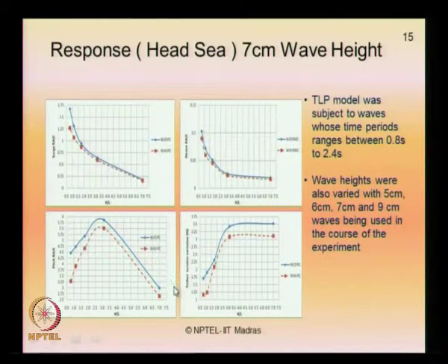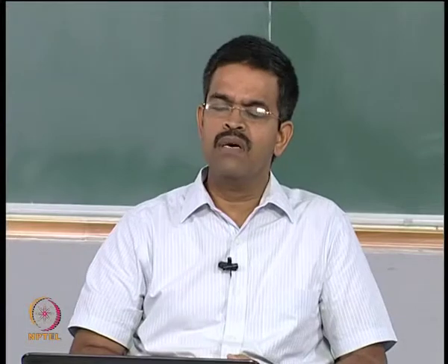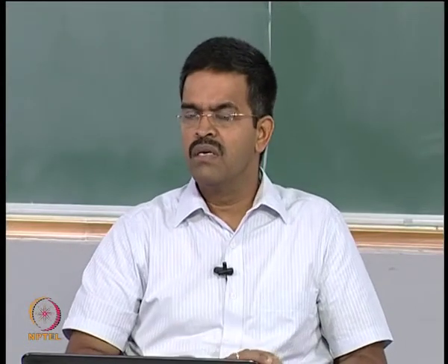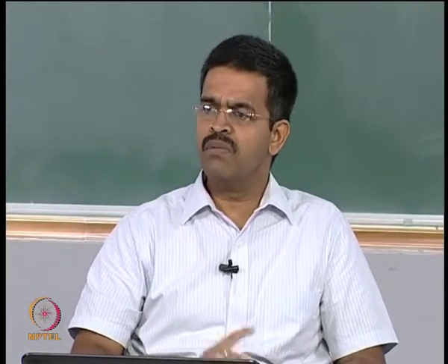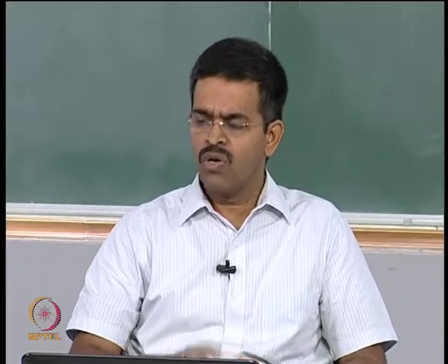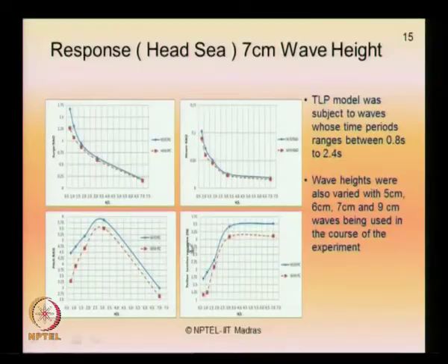Interestingly, you will also see that the tether tension variations, that is the tension variation in tethers or cables, are also significant. For higher H by L values the reduction is significant. So, a perforated cover or perforation layers encompassing the inner cylinder not only decrease the response of the members in the inner cylinder, but also decrease the tether tension variation.